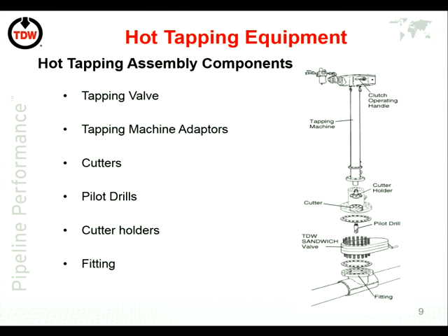You then got what is called the cutter holder, and then you've got the cutter itself in this area, and it has a pilot drill, because if you're drilling a big hole, it's not a drill, it's a cutter, but you need to have the central pilot drill to keep it in the middle, and that also acts for another reason which I'll come on to later.